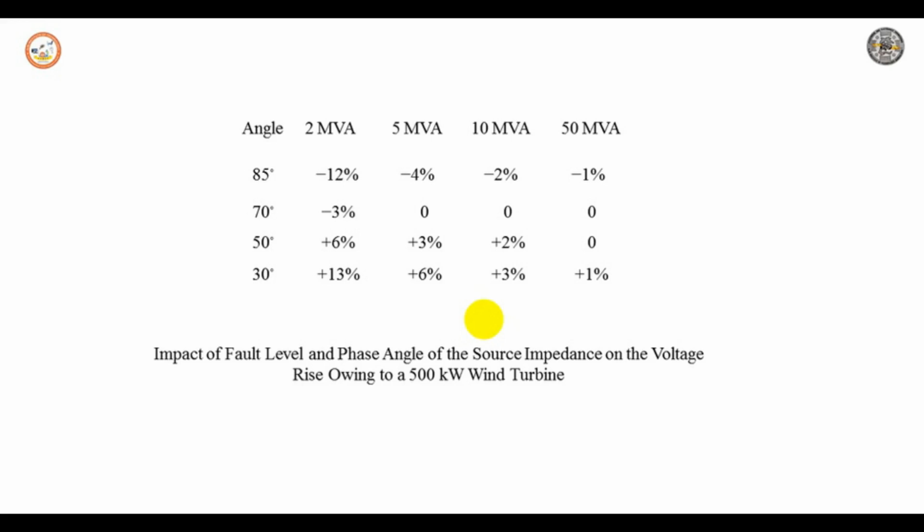The use of shunt or series capacitors for voltage control will typically result in higher hosting capacity. This also depends on the control algorithm used. When the capacitor banks are switched on the basis of reactive power flow, this may further deteriorate the overvoltages.